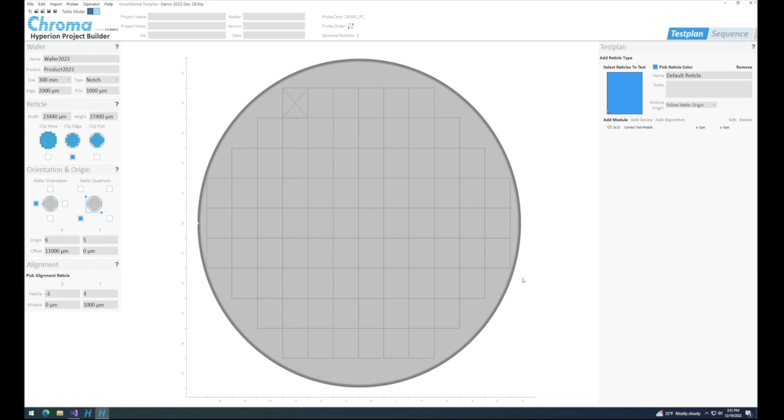Orientation defines the direction of the module. This is only for wafer probers which can accept alignment files specified by name or by data downloads over GPIB. This feature allows both horizontal and vertical scribe lane test structures to be automatically accessed within the same test plan.